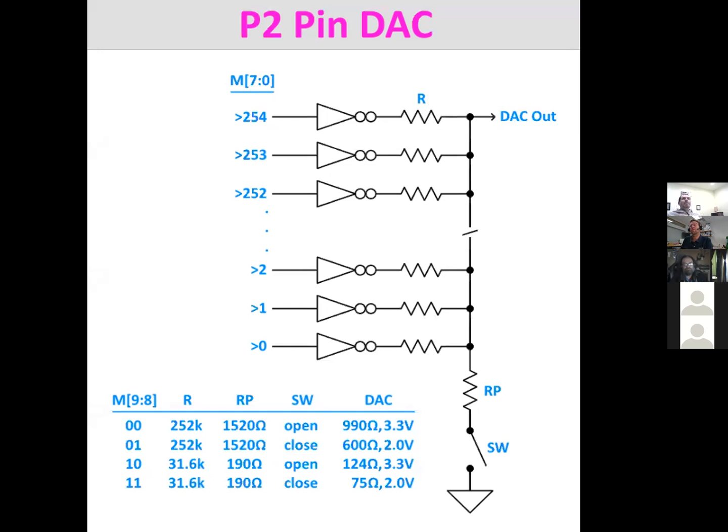So they're pretty limited. However, we have smart pin modes which can dither the DAC between 2 adjacent values. Like if you want to output, let's say we have a 16-bit mode, right? So if you want to output 80 hex, well, that's actually between 0 and 1 on the 8-bit DAC. So what it would do is spend half the time outputting 0 and then half the time outputting 1, which would be realized just by this bottom inverter toggling at 50% duty cycle. And that would actually create a half step between value 0 and value 1.